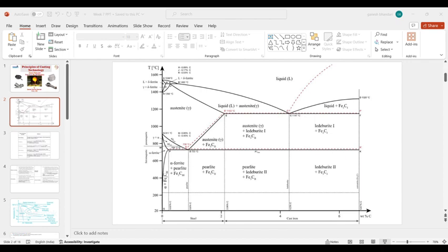If we want to use our steel in aircraft applications, and we are talking only about mild steel, not stainless steel, then you have to go with bainitic steels, because they have the highest toughness properties in comparison to pearlitic steel, martensitic steel or other types of mild steel.